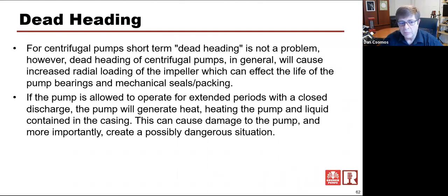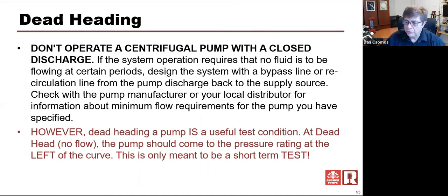Again, you don't want to operate there very long. You want to take a quick run to deadhead by closing a discharge valve. Never close a suction valve, ever. Close a discharge valve to cause a deadhead, and take a quick pressure reading and maybe a quick amperage reading. So hopefully that will help you diagnose a pump too.